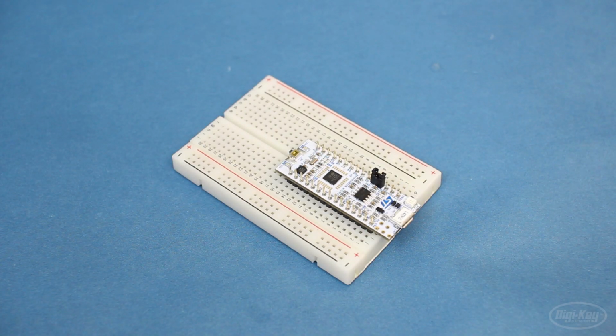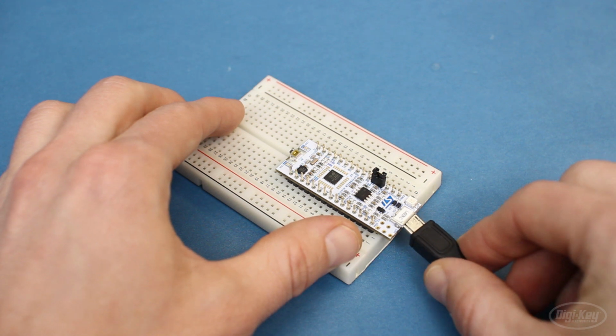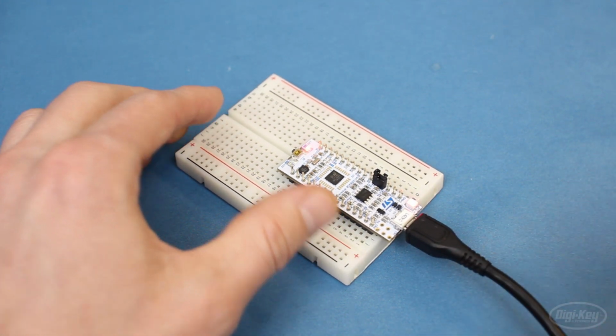For this example, I'm going to show you how to import TensorFlow Lite into STM32Cube IDE, and that's only because I'm most familiar with STM32 stuff right now. I'm using an STM32L432KC Nucleo board for this, as it's small but running an ARM Cortex-M4 processor.